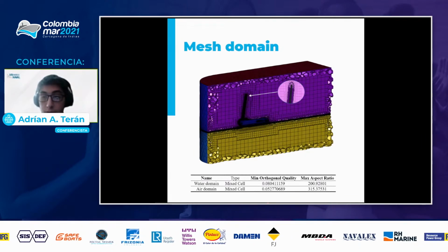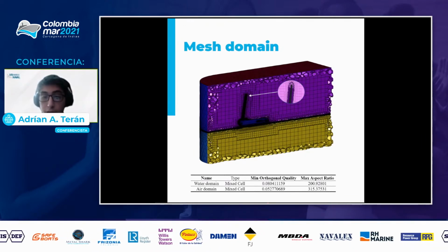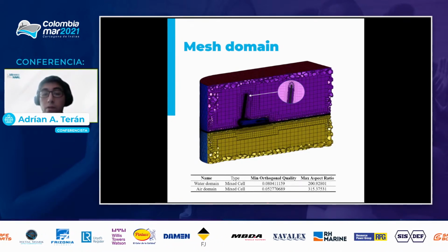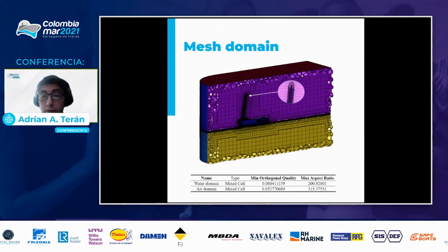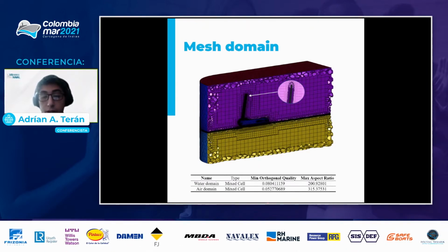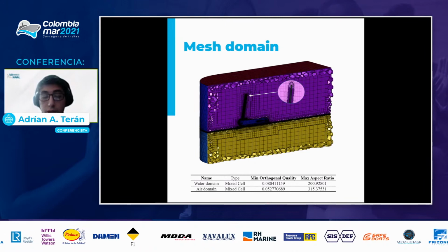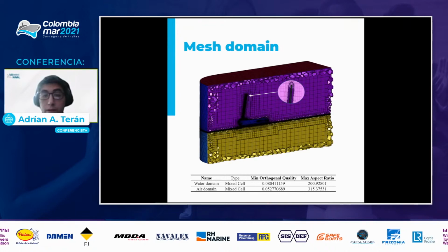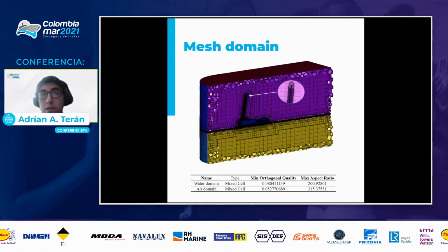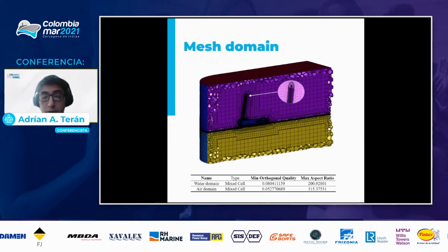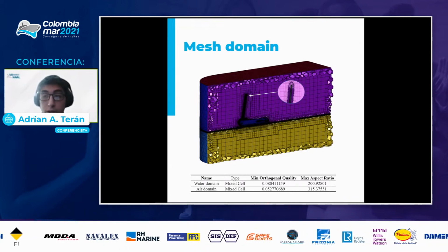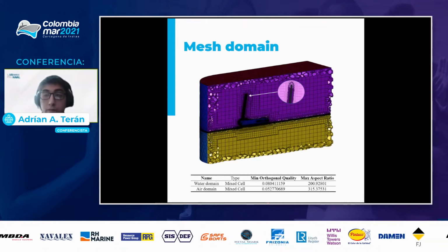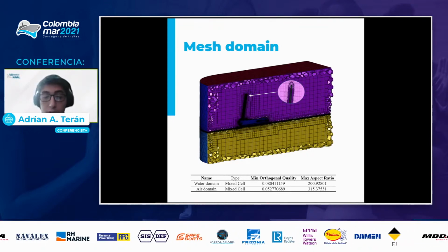Of course, these meshes are of high quality. They can be measured. The main metrics have to do with a value between 0 and 1 for the mesh. These metrics are supposed to be at 0.15 ideally, and so forth. Around the mesh, the metrics will vary depending on the elements. The lowest values can be reached as long as prism elements are used, which is always necessary, particularly within these kinds of phenomena.